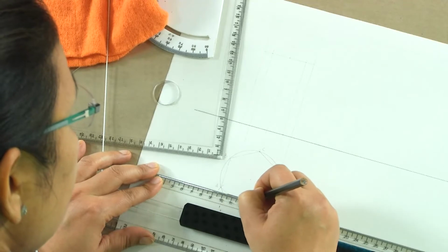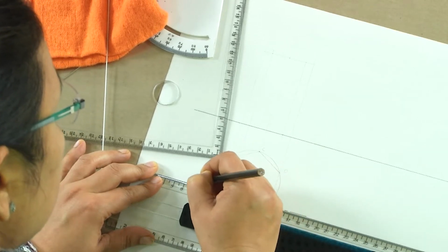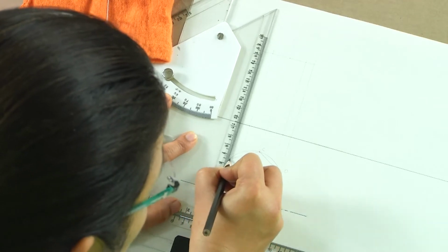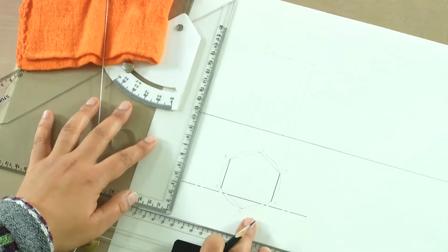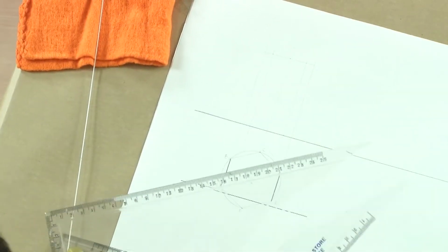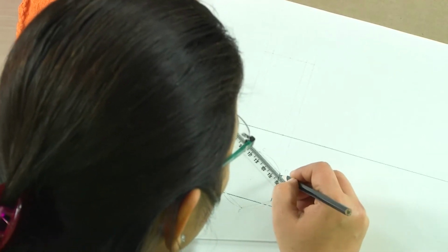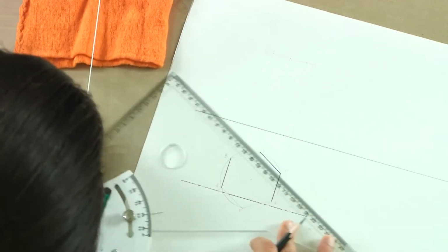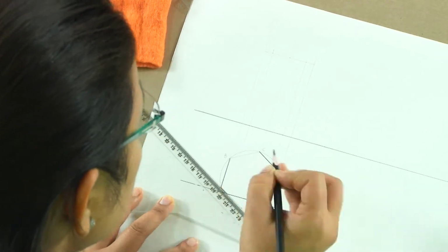So, what do we have finally left? We have this section plane. This is the nomenclature that we use for marking the section plane. The leftover portion of this hexagonal prism as seen from the top is only the one which is not cut. We are assuming that this portion, the bottom portion, is taken off. So, we will not darken the portion which has been cut. I am only darkening the portion which we are keeping or which is still there.